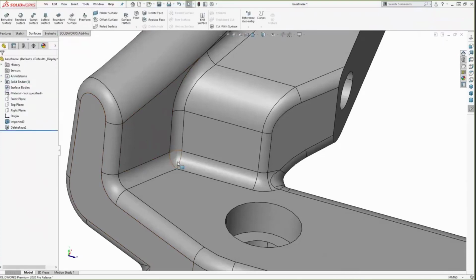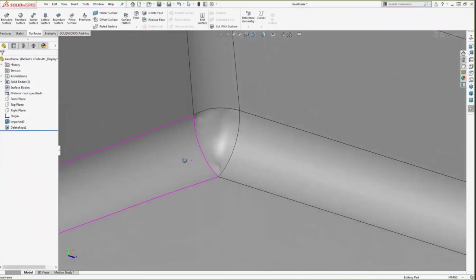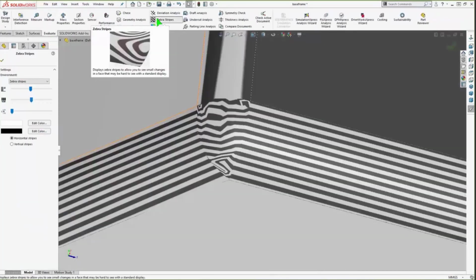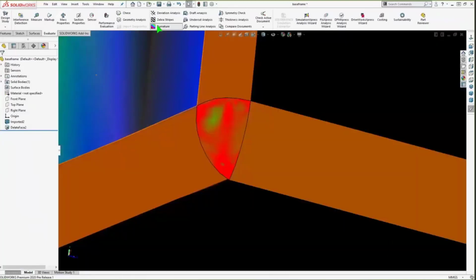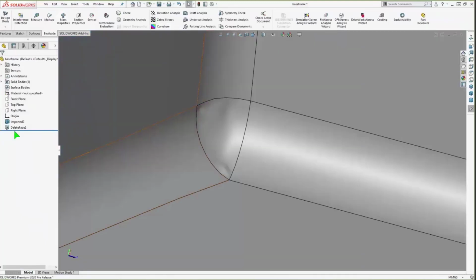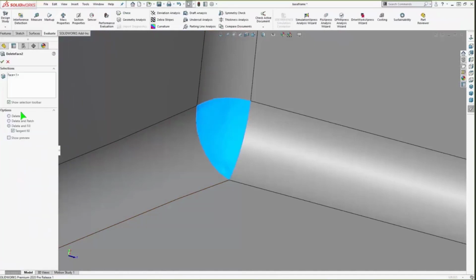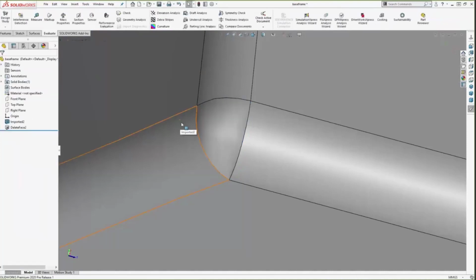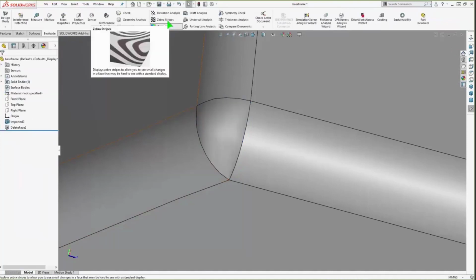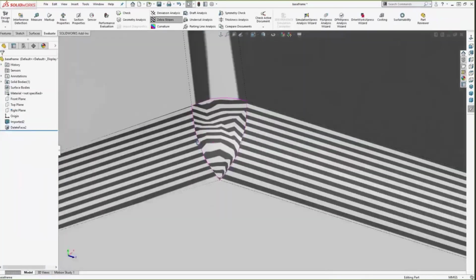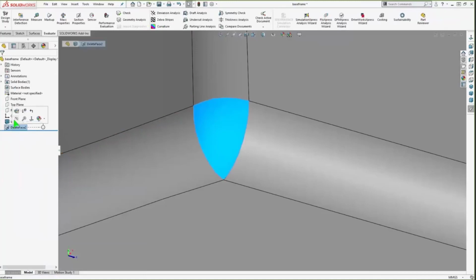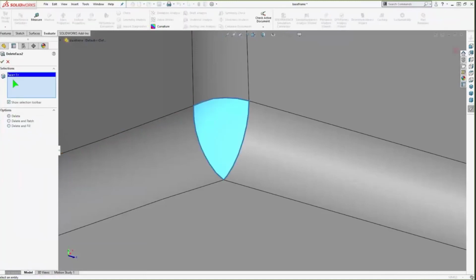This delete and fill, it's almost like it's doing a filled surface command on that new gap. And you can see that doesn't look too good, right? Topology, it does close the gap, but the geometry there, like that face, looks pretty awful. So that one's not great. We could try turning off tangent fill. These are like the easy methods, easy things to try. It's just a step or two, but looking at the zebra stripes might give you a little bit more indication that it's not really a smooth transition. So good try, but didn't quite do what we want.